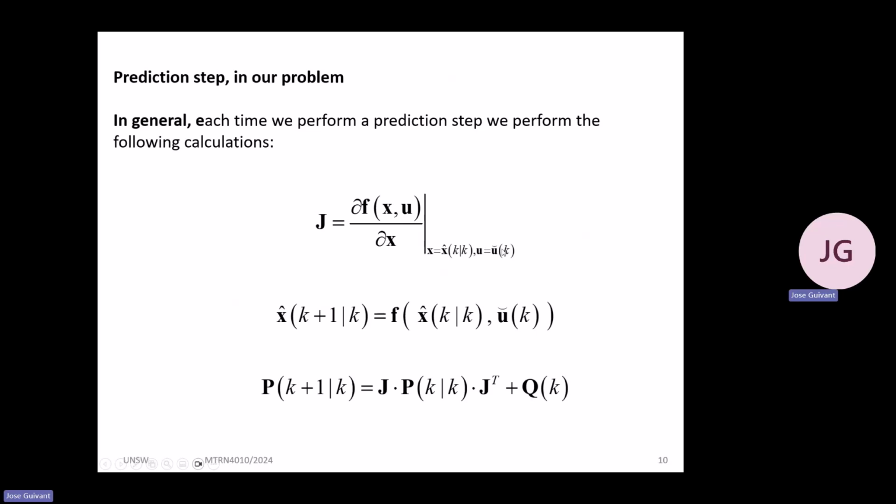The expected value of the input is what I measure. I do know they are sort of wrong and they follow some Gaussian distribution, but for me, that is my expectation about the measurement happening now. So this Jacobian, which I call Jake, after evaluating that analytical expression in current expected values and the current measurement of the input, that will be a matrix Jake, which will be square, and it's going to allow me to obtain the new covariant after applying the model.